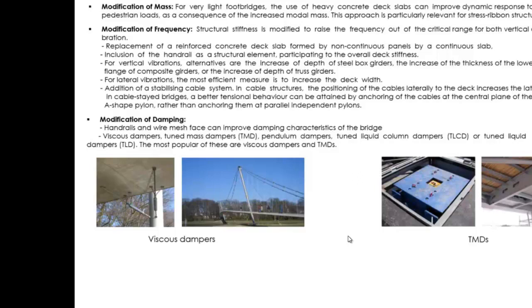Let me briefly cover what we have covered in today's webinar. First we saw the various challenges which engineers face in the design of footbridges. Then we saw the basics of dynamic analysis and the various codal requirements of Eurocode for dynamic analysis. Then we moved on to free vibration analysis of the bridge, and then we defined the time history load case, load function and dynamic nodal loads, applied them on the structure, saw the response of the structure and peak acceleration, and compared it to the codal limits. I tried to cover as much as possible about dynamic analysis. I hope you enjoyed this webinar and it was helpful for you.